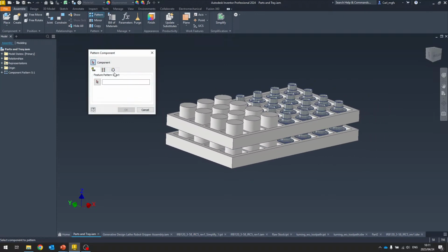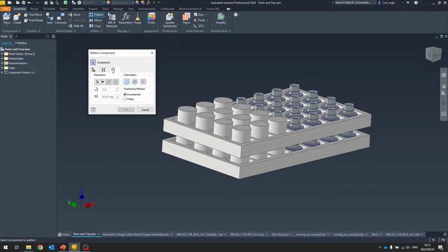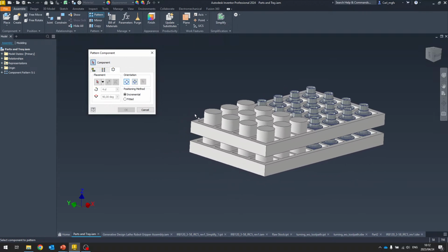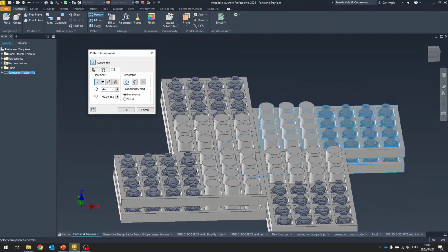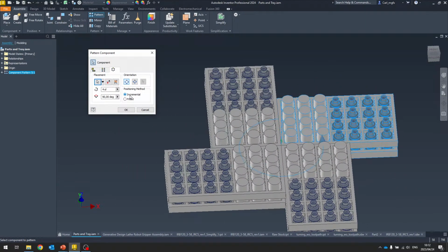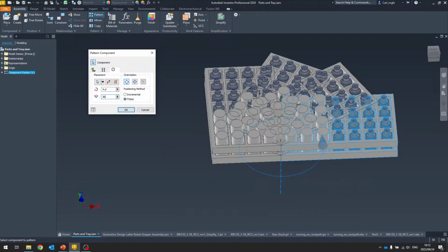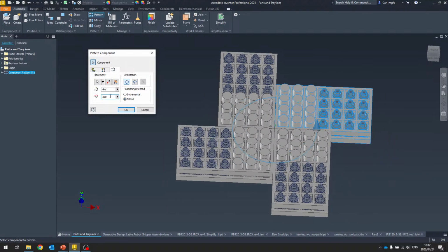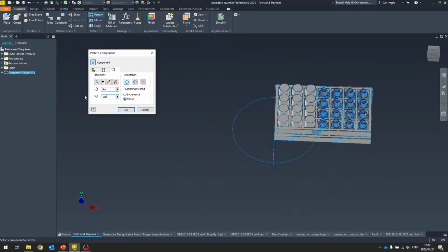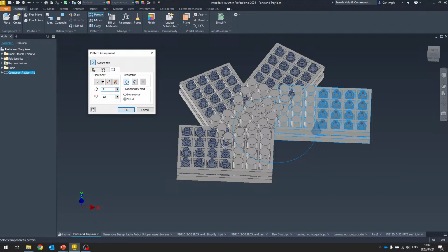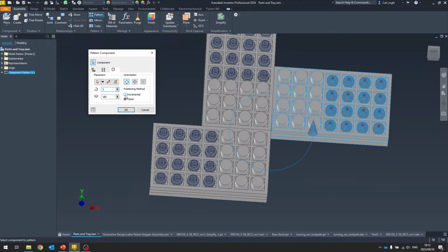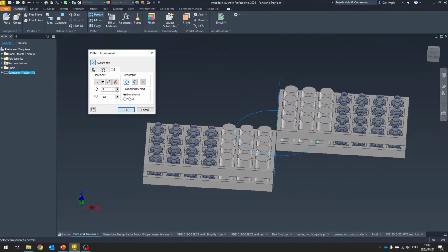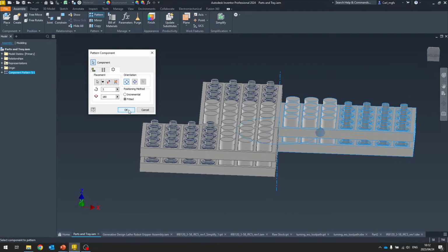And then jumping back into the pattern command, we'll go to the circular pattern. We can grab those components once again, select an edge to pattern around, and you'll see that we have the increment, or we can do the fitted. And so we can adjust the values as required to get those components to be either spaced with an incremental value or a fitted value.